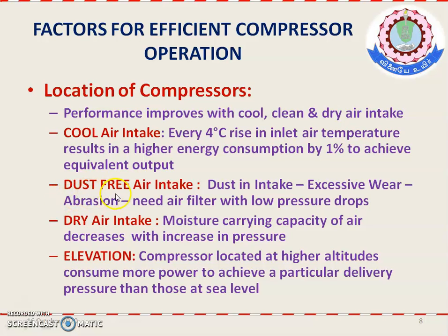And similarly, dust-free air intake. With dust intake, excess wear and tear will happen and you need air filter replacements or other things, and that's why dust-free air is important. Dry air intake: moisture carrying capacity of the air decreases with increase in pressure